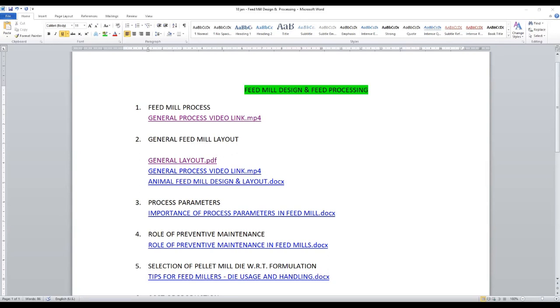Same in small warehouses, in relation with this, we can multiply by 7, because as the warehouse size becomes smaller, the area required for the passage, ventilation and the movement remains the same, so the stacking efficiency reduces. The smaller the warehouse, the lower the stacking efficiency. So where we took a factor of 6, sometimes we have to take 7, 7.5 and even 8.